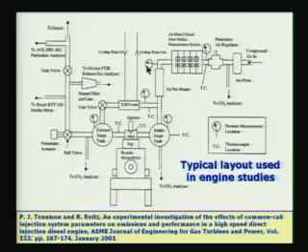In a later lecture we will also look at a similar situation, and we will see, for example, here there are so many pressure gauges, pressure transducers, there are many thermocouples, and there are other devices to measure air mass, air flow, and so on. All these require simultaneous measurement. So one cannot of course go on taking readings. In the earlier times we used to do that. One student will take the reading here, another student will take the reading here at the same time, and so on and so forth. Now we do not do that.